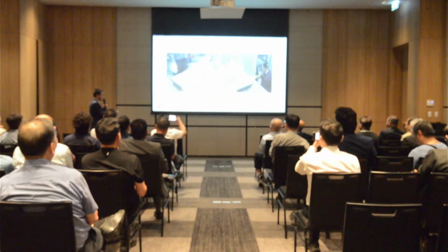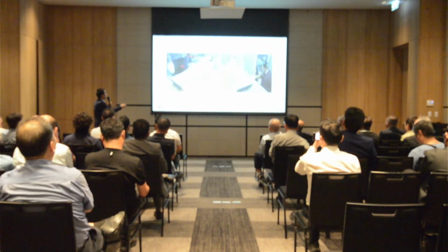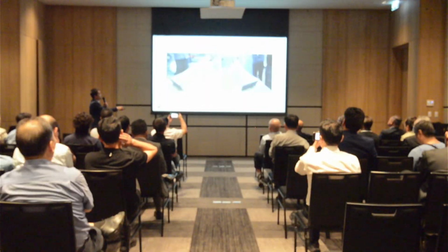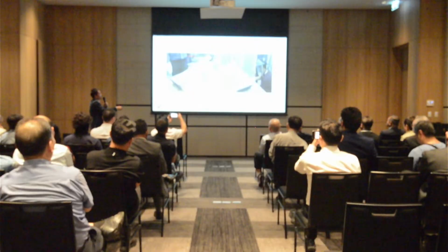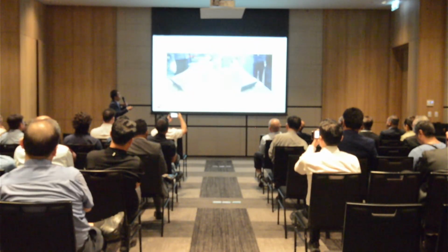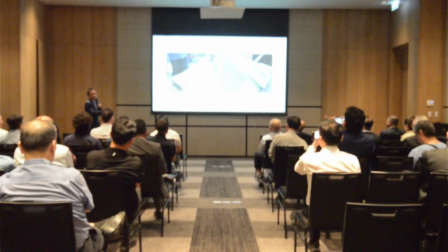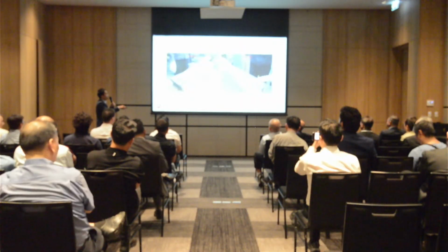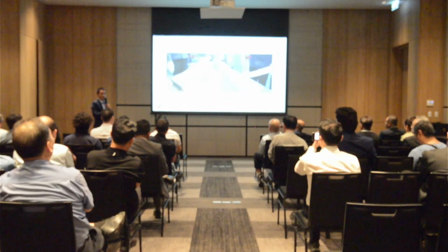And that's why we call it the viscosity control process for slurry optimization, process combination. Here you can see this is liquid, fully liquid flow. When it solidifies, the outside is solidified, the inside is still liquid. We will get shrinkage. But for this flow behavior, similar to filling your die or filling the shot sleeve, the solid fraction increases as it cools down, giving higher viscosity. You can see the flow is a totally different flow behavior. With the same gate velocity, high viscosity gives less turbulence. And then when you continue cooling down, you get high solid fractions. This also explains how to reduce shrinkage porosity: the inside and outside solidify uniformly, not like the outside solidified and the inside still liquid. That's why we can reduce the shrinkage.